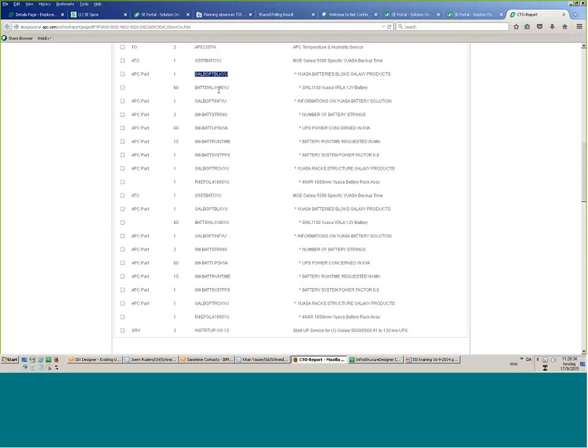They know how to calculate the interconnection cable, and they actually also double check us. Then we just have startup here, and then down here I have a big description of the UPSs again. Name of UPS, what I have chosen, selected, requested 15 minutes, I actually get 17 minutes, DC load, and it also says here that the assembly service of the batteries and battery rack is not included. And then I also have battery rack information. And down here the floor layout. Good.